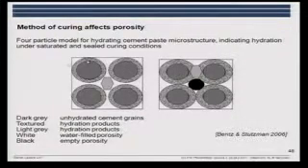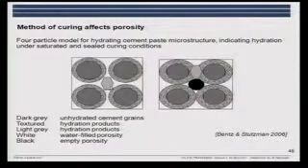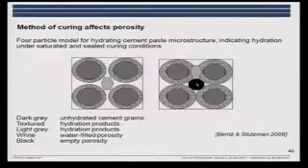If we have a system where we have sufficient water, it's saturated, so we have water coming in. The hydrates outside the grain can precipitate where there's a sufficient or large amount of space. If, on the other hand, we have a system where we have self-desiccation, the large pore here is empty, no water, and the hydrates will precipitate in other places. If, for instance, you consider these two structures and you are having chlorides ingressing, you will see that in this situation, chlorides can actually go much more easily in than in this.